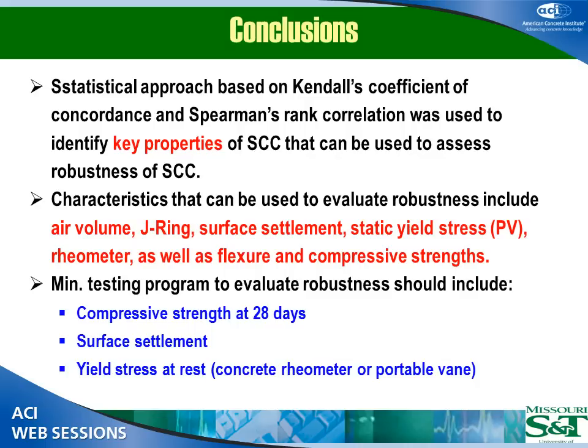Actually, the polycarboxylate we were using gives you inherent viscosity. And you know that. That's how you design it, right? So it takes care of the stability issues. But the variability, I mean, as you know, the response with PNS is pretty linear. So you add more, you have lower yield stress, higher slump flow, you add a little bit more, it's pretty linear. But with polycarboxylate, it's not linear. It's linear initially, but then it goes exponentially, and then it goes back to linear. But that exponential is what throws us off. And obviously we are within that range. That plus or minus 10%, or plus or minus water content, that makes them more dispersed or less dispersed is throwing us off.